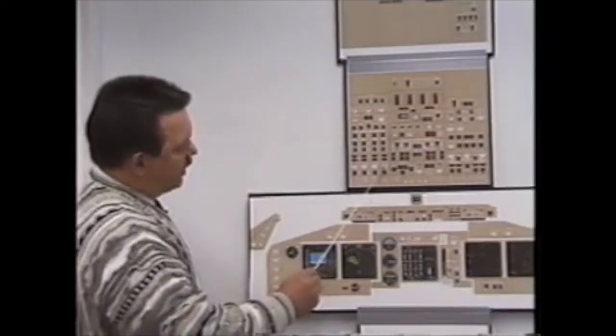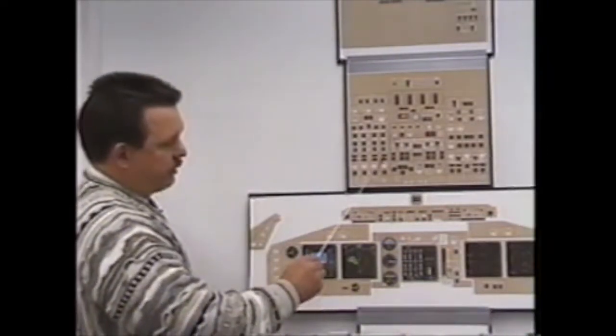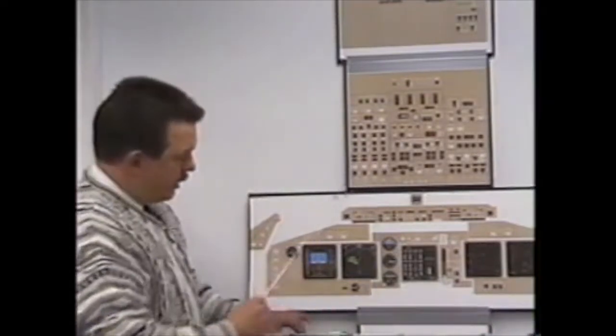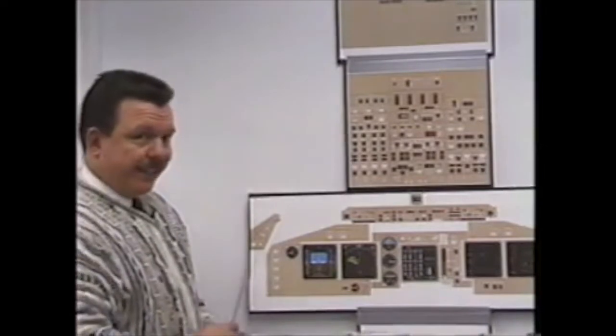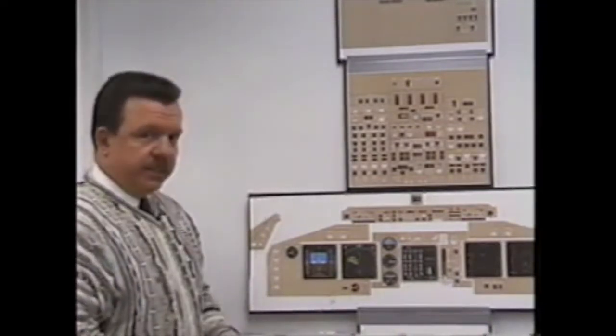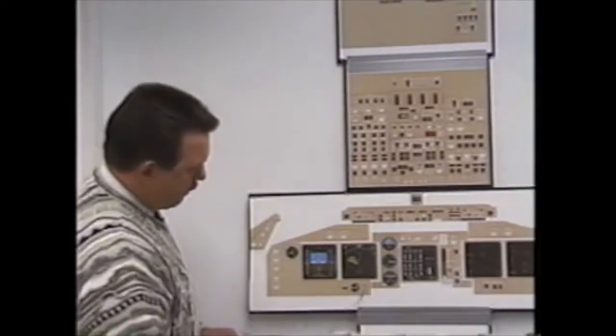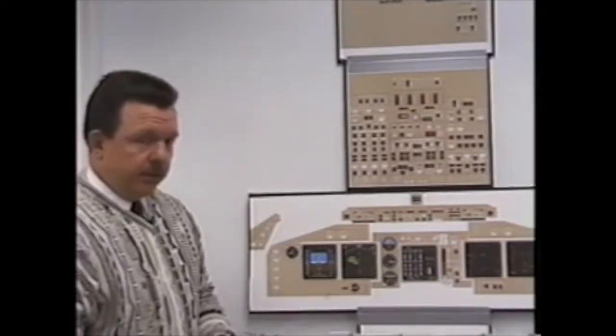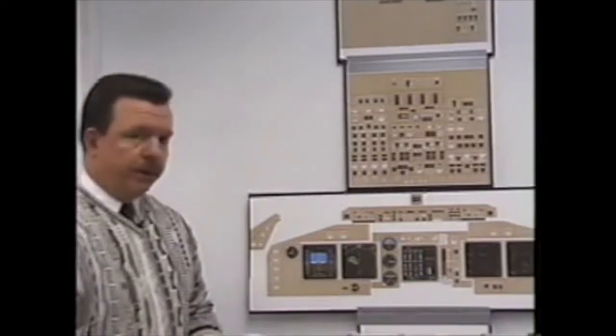Now if I was to then reach up and kill System 4, I lose system pressure in 4, the brake should go to alternate System 1. But my brake source light illuminates, indicating that change did not occur. So as a result, my brakes are right here on the accumulator, which is not going to stop the plane. The accumulator is designed to set and hold the parking brake only.